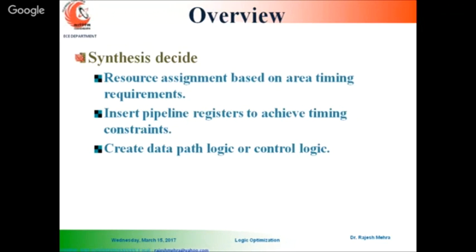If timing is not of major concern, then you can reduce the number of resources. You can go for serial kind of architectures. In that case, you can make your design cost effective and area effective, but you have to compromise on speed. So depending upon the requirement, you can allocate the resources, and you can control the timing options in your design.